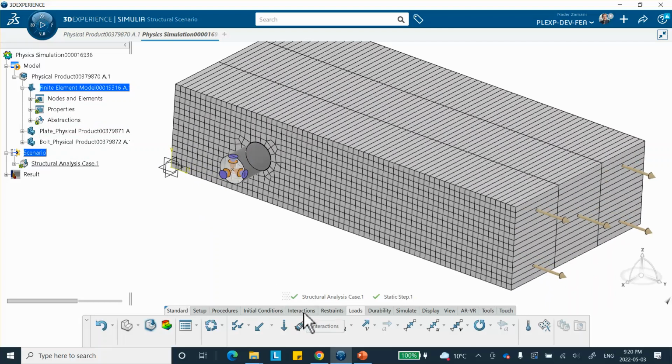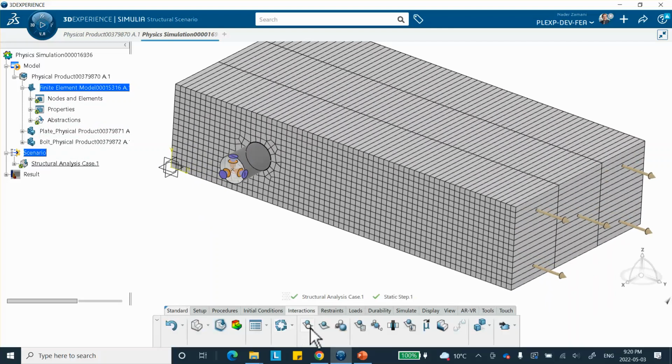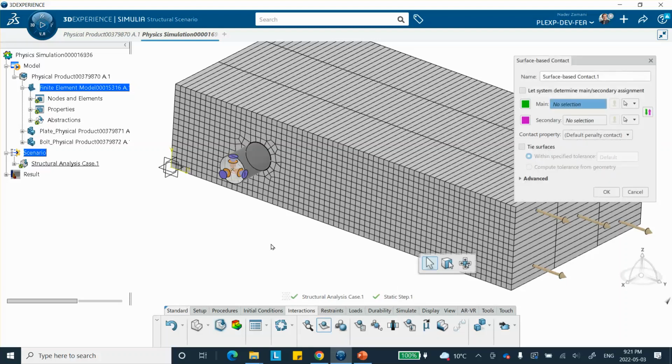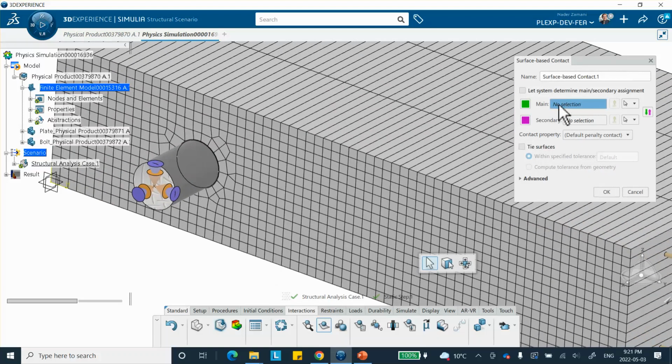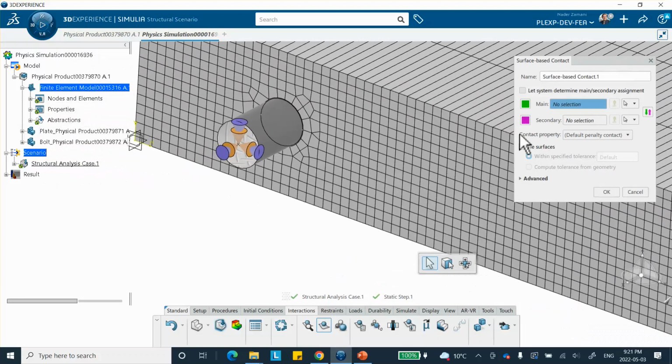So here's the interactions tab right there. First of all, defining surface to surface contact, you click on it. For the master surface, or the main surface, you take the more rigid one, or the one that's finer in discretization. Now, we did not discretize this because it's an analytical rigid surface, but it is rigid.